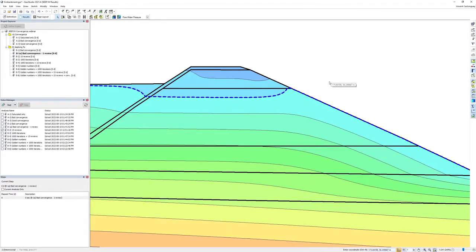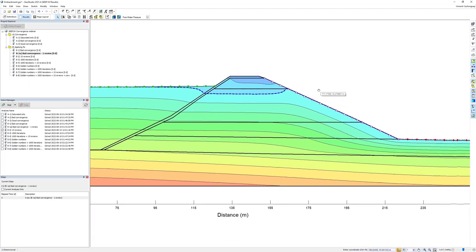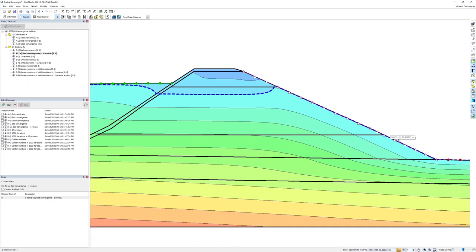the downstream portion of the dam. The phreatic surface seems to be climbing upward as it prepares to exit the dam, which is very suspicious to say the least. If I display the boundary conditions used in the analysis, we will recall that the drainage boundary condition was used on the entirety of the downstream face of the dam.